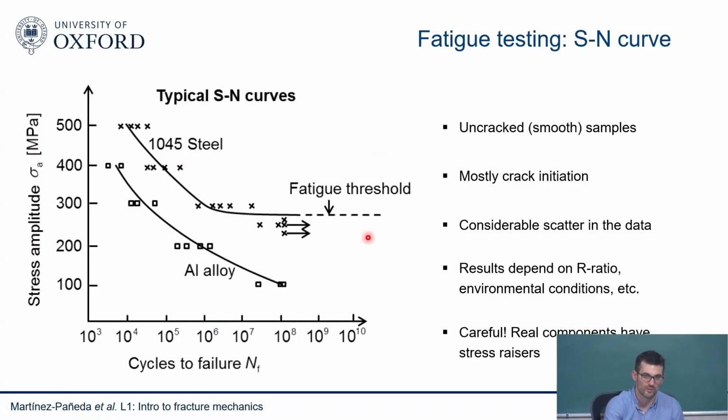This is uniaxial, 1D. In reality, stress components have a stress tensor, so you have to do a finite element analysis. You get your stress, and even though your applied load might be here, your stress tensor might take you here, so you go and test what is the effect of the stress tensor.